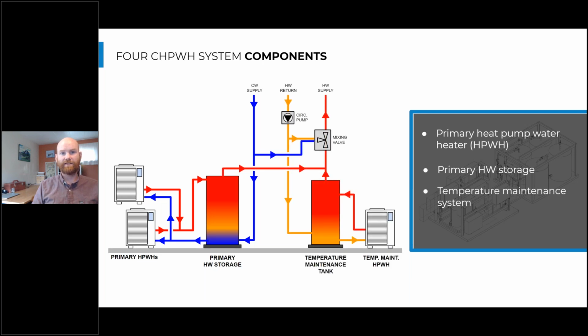And we also discussed the temperature maintenance system in session 1 and what it is. This is the distribution system in the building that's piping hot water to those end use fixtures. Typically, we circulate that piping to maintain the water near 120 in that entire distribution network. So we circulate it at a slow flow rate. Well, we learned that that can present issues to certain types of heat pump equipment, and it might be more reliable and more of a robust solution to separate out that temperature maintenance load with a dedicated temperature maintenance system.